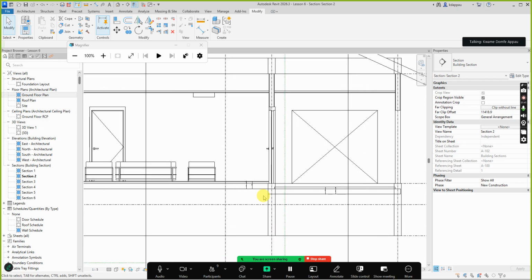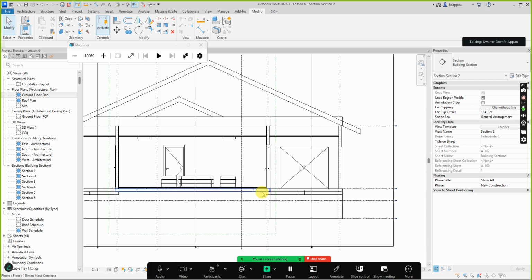When we are producing architectural drawings, there are different sets of drawings that we produce. We produce general arrangement drawings, like floor plans, reflected ceiling plans, sections, elevations, and so on. We also produce details, and the details include enlarged views, that is enlarged floor plans, enlarged sections, enlarged elevations, and so on and so forth. Then we also produce assembly details. We produce component details. Then we can even go to the extent of producing sub-component details.